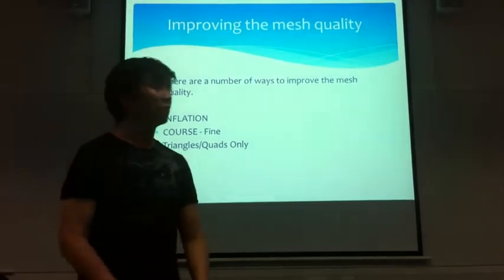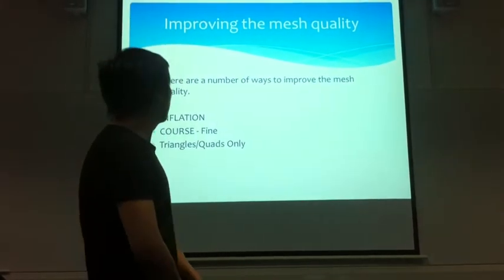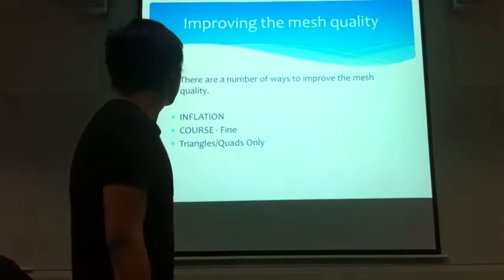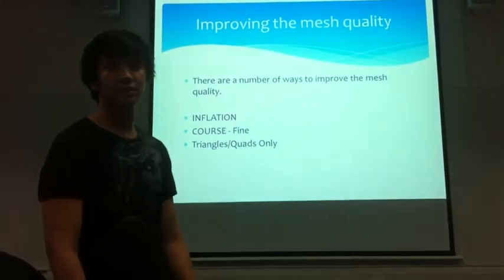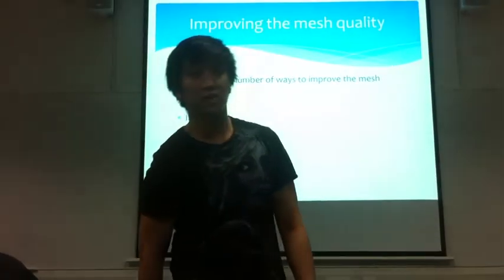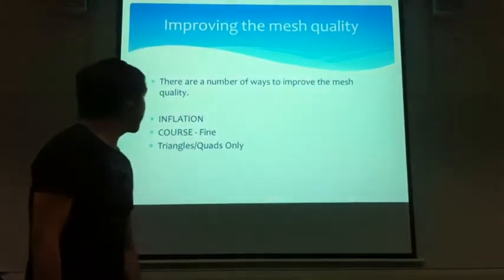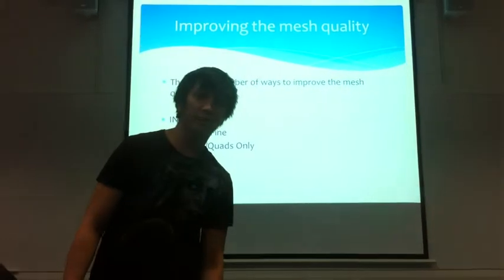There's a few ways of improving the mesh quality. You can inflate it using the software ANSYS, as well as change the coarse to fine. However, this will impact the time spent on making the mesh, as well as making quads, the mesh type as quads.